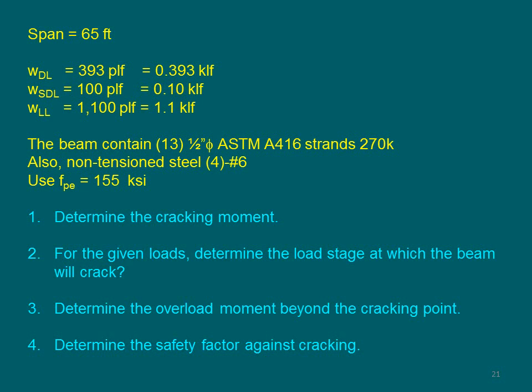I have also non-tension steel. It's going to be conventional rebars. It's going to be 4 number 6s. And it tells me here to use FPE of 155 KSI. Effective pre-stress is going to be 155 KSI.